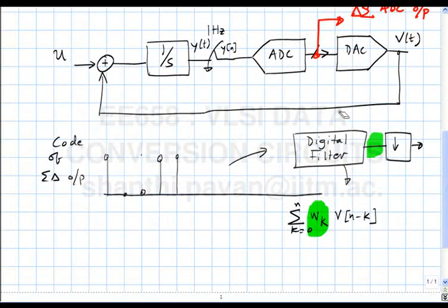So how do you think you'll implement a discrete time filter? One way of implementing discrete time filters is to use switched capacitor techniques, where everything is sampled but the amplitude levels are all continuous. There is a big distinction between the two. Does that make sense? Alright.